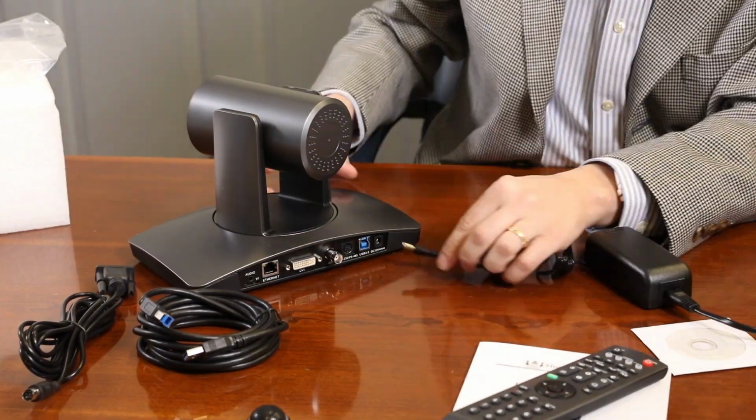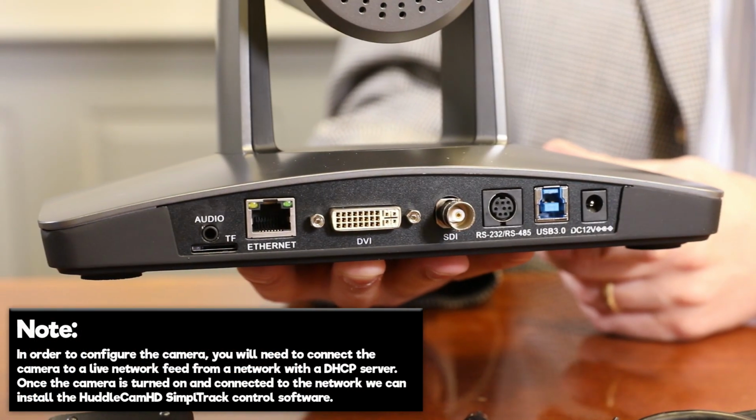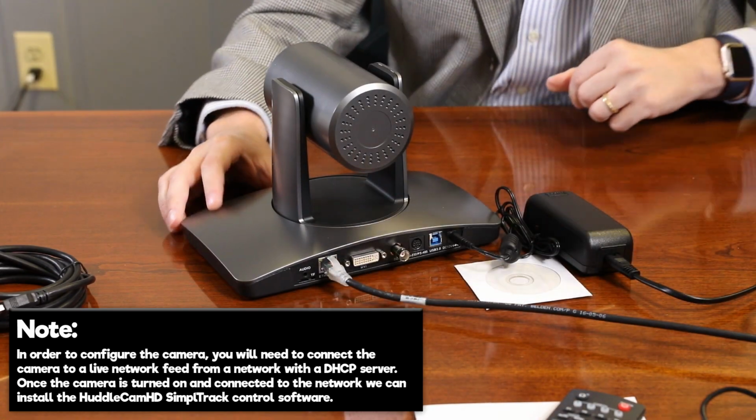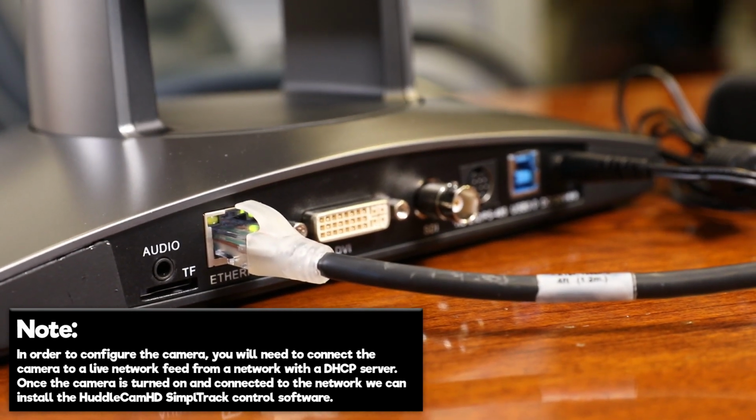Now it's time to plug your camera into power with the included power supply. In order to configure the camera, you will need to connect the camera to a live network feed from a network with a DHCP server. Once the camera is turned on and connected to the network, we can install the HuddleCamHD SimplTrack control software.